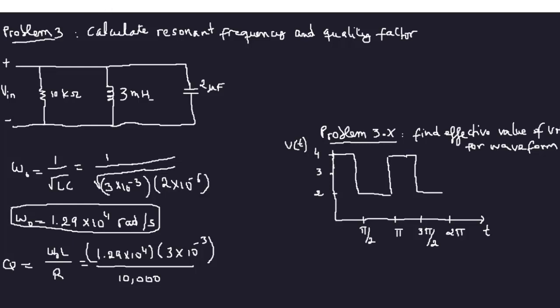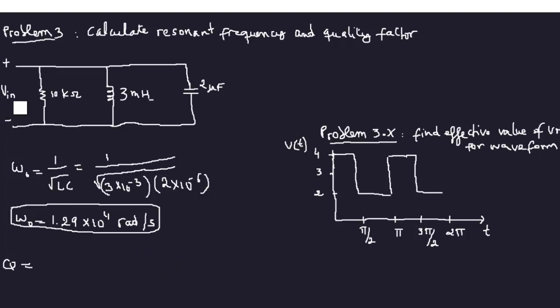Okay, this is for this formula right here. There are two, which is why I was a little hesitant, because there are two formulas for quality factor, one for series and one for parallel. And over here we're dealing with a parallel resonance, so it's a different formula. It's the first one that I wrote. Yes, so this is R over omega 0 L. I wasn't reading series versus parallel. Now I got it.